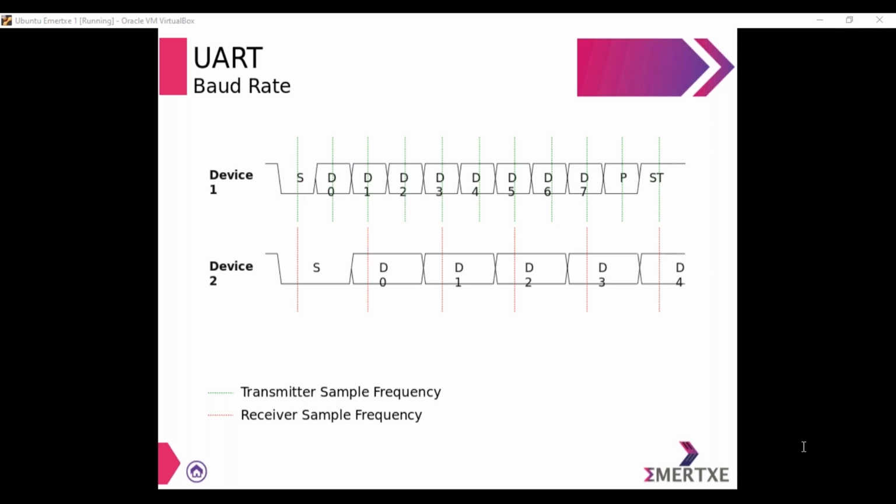In synchronous communication, you may transmit the data, you may receive the data. The master will generate the clock pulse and accordingly transmission and reception happens. So there the clock frequency is important. You have to look at what clock frequency the device can communicate with. Accordingly, you have to set the clock frequency.